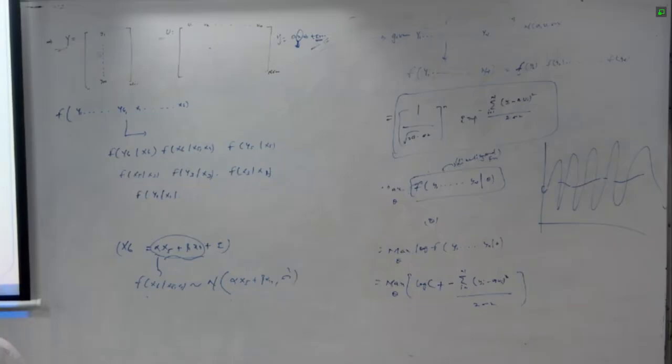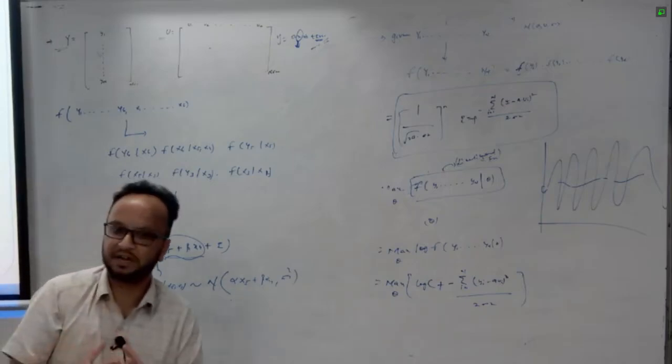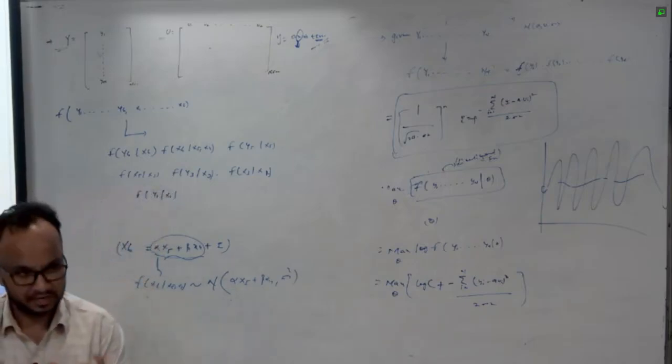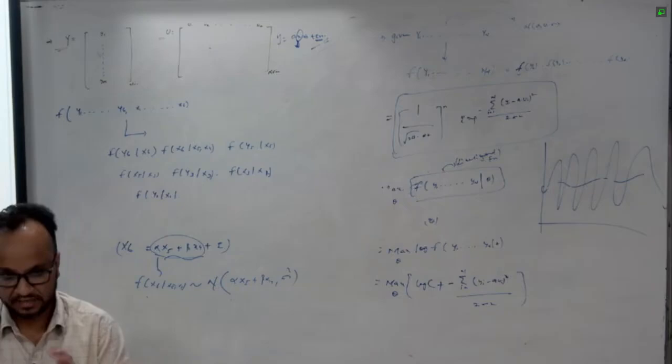The easiest way is to consider the nearby points and model it, because the process conditions keep changing, the locations keep changing. That's what we call local modeling. I only search the nearest points around it, rather than considering the entire global data, which can be suboptimal. How do I get the nearest neighboring points? I use KNN search, with Euclidean distance as the distance-based criterion, search the nearest data points, pull them, get the input data and output data, and fit a model between them.